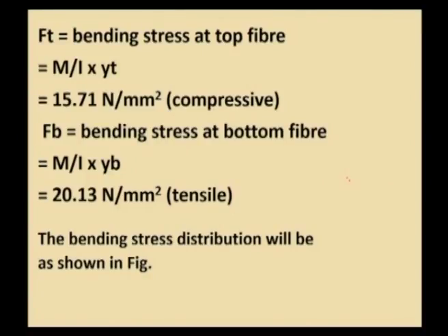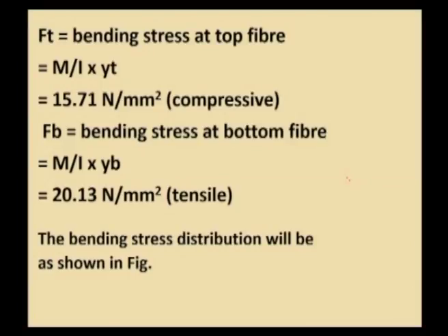So, we know that for a simply supported beam subjected to any loading, the bottom fibers will be subjected to tension, and above the neutral axis, or centroidal axis, we will be having compressive stresses. So, the bending stress distribution will be as shown in the figure. Say we need to plot the bending stress distribution for the I section.